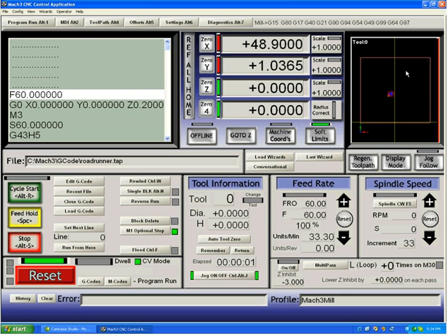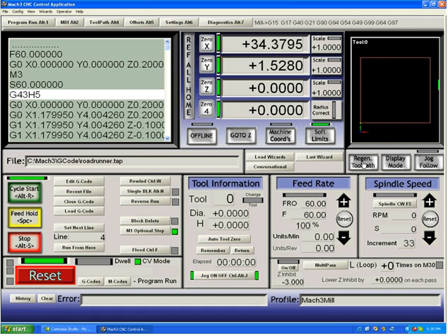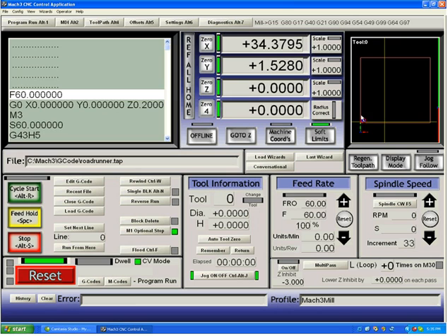Now we're going to hit our switch. The switch went active. We changed directions and it just moved off the switch. When that occurs, the x-axis begins its movement towards its home switch. Now I have a simulated table here, so I'm free to press the home switch whenever I like. So I'm going to press the home switch now. The axis reverses direction and the home switch releases, and we're now homed. And you'll notice that the lights are green. Green means that you have successfully homed the control. Hitting Regen Toolpath will show the toolpath at its new location because the home has changed.